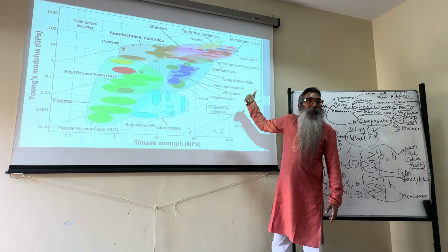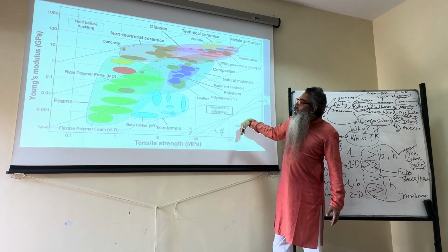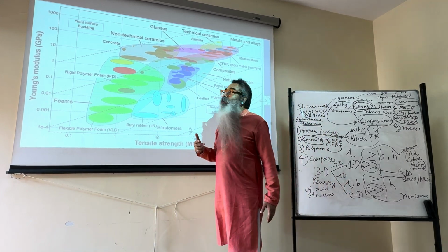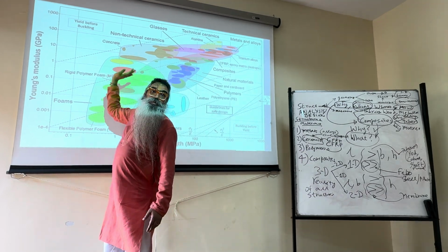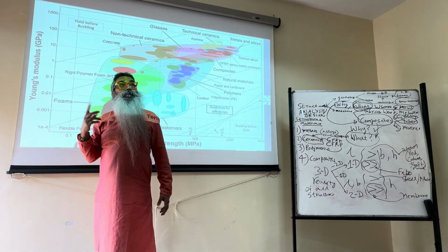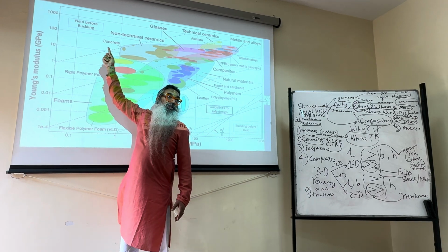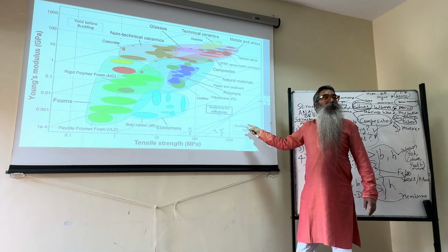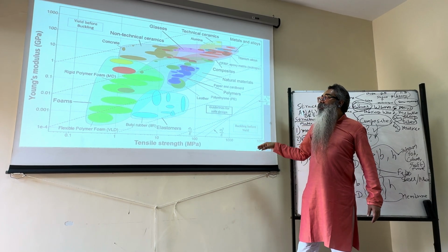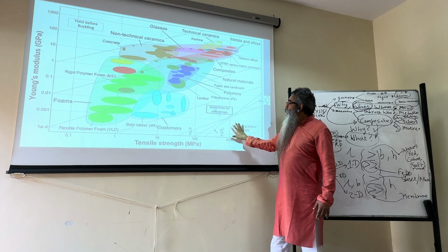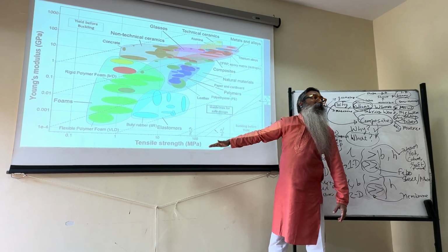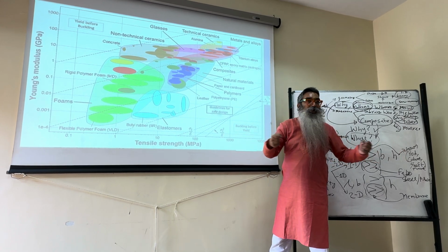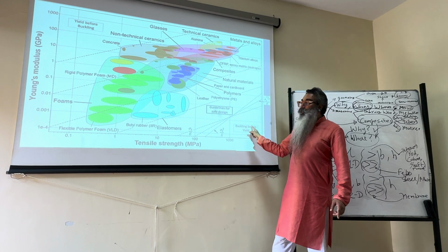But one of the things that it distinguishes on either side of some of those lines is which of the failures will occur earlier. See, for most of the materials on this side, you will have the material failure occurring before the geometric failure. On the other hand, here you will have the geometric failure occurring before the material failure. So that's essentially what we're talking about. Why? Because you see in this range, the Young's modulus is very low. So in other words, stiffness is very low. For the same stress, you'll have larger deflections. So the chances of geometric failure are much more over here.